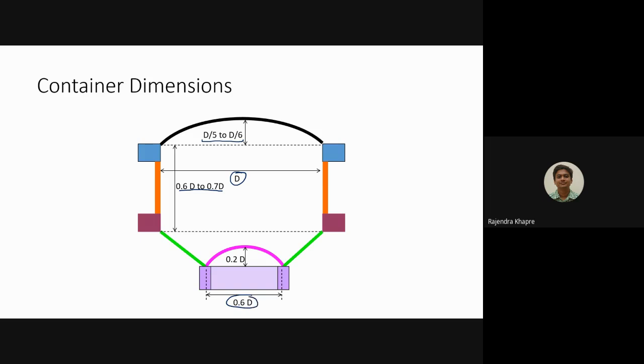So these dimensions mostly are given. If they are not given, you have to identify them using these standard formulas. Okay. Usually this angle is 45 degrees. So this conical dome is usually kept at an angle of 45 degrees so that the forces can be distributed properly, right?